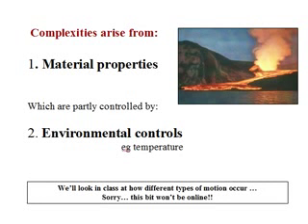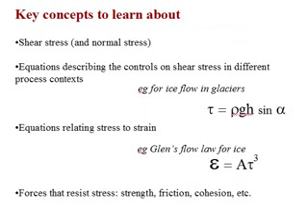To see how gravity is involved in these processes, there are some important concepts we need to find out about. Shear stress is force applied parallel to a surface, like the force that makes a glacier slide over its bed. Normal stress is a force perpendicular to a surface, like the weight of that dry stone wall on the flat floor beneath it. Gravity acts perpendicular to a horizontal surface, but where the surface is at a gradient, gravity includes a component of shear stress parallel to the slope. As gradient increases, the shear component of gravity increases.